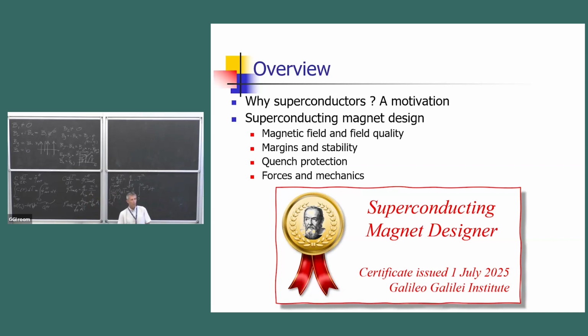So what was not understood at that time is that that part of the spectrum was associated, as an example, with mechanics, and in particular with the fact that the windings, although they're well made, may still have porosity when you impregnate and pot the coils, or there may be locations where the wire is not properly supported. So under the electromagnetic force, the magnet tries to expand, breathe, and then you may get cracks in the epoxy, micro movements, stick and slip, and then the wire generates some energy, quenches, but then it locks into a new position.